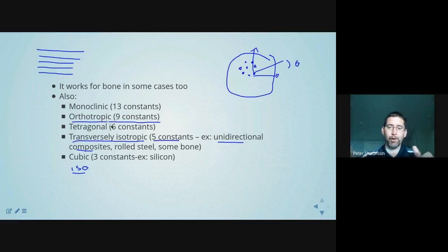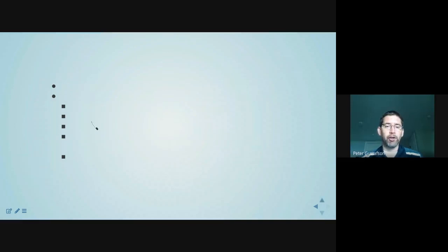whereas transversely isotropic, or orthotropic, if you cut it along the fiber direction and pulled that coupon, it would give you one response. If you went at 45 degrees, it would give you a different response. If it went at 90 degrees, it would give you a different response. So all of the materials except isotropic now depend on the actual magnitudes of the coefficients, depend on your defined coordinate system. So as you rotate coordinate systems, be aware that the relative magnitudes of the coefficients change.